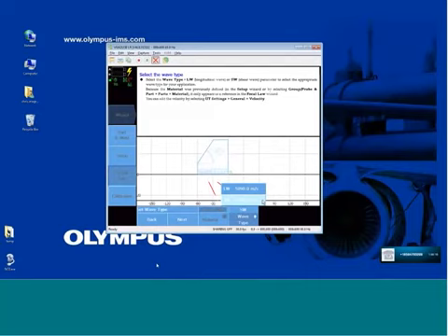I can calibrate or measure the velocity using the calibration block and the calibration velocity wizard. More than likely for carbon steel, we're going to be better off using the database velocity because your ability to measure it within 25 or 50 meters per second is very much suspect depending on the type of probe and calibration block you're using.